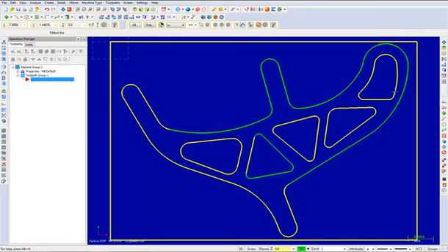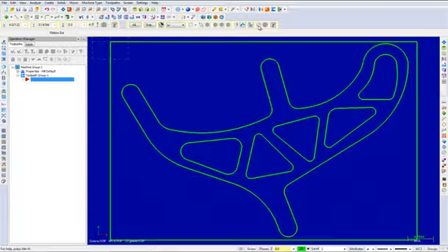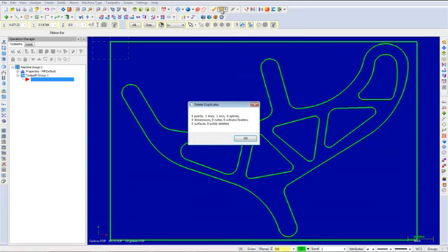For Mastercam to automatically remove all the duplicate entities from the current file, make sure that no entities are selected. To do this, click the Unselect All button as shown. From here, choose the Delete Duplicates icon. This message will appear on your screen. Mastercam automatically removes all the duplicate entities.